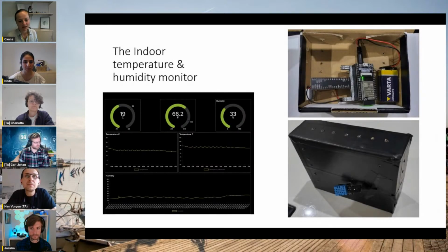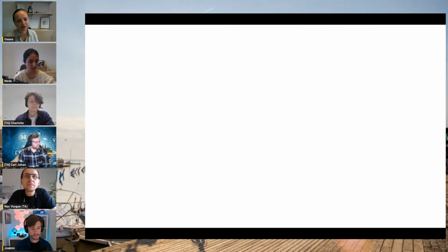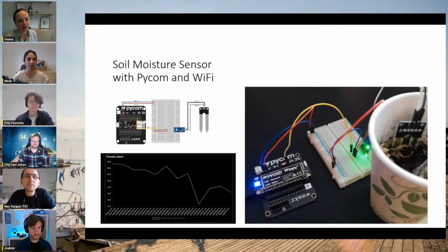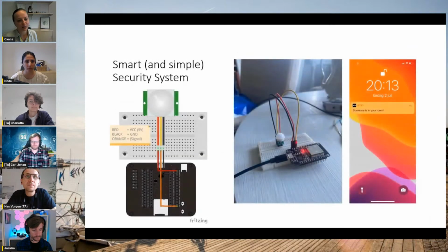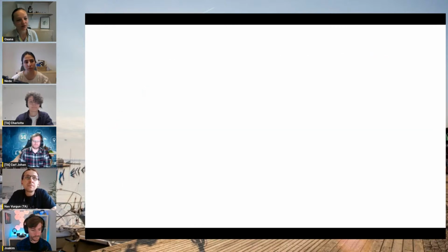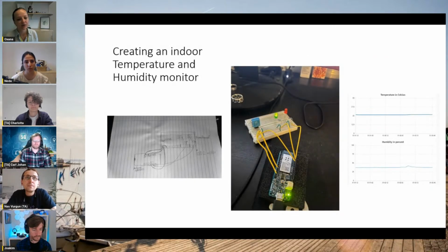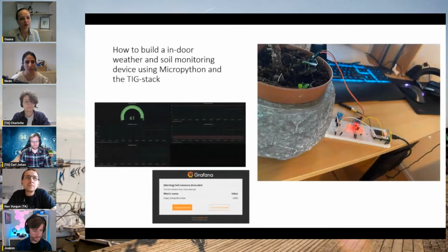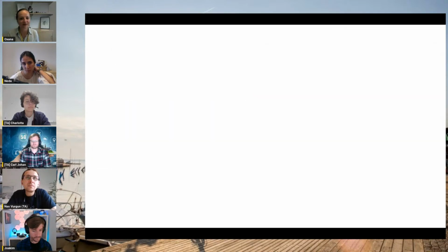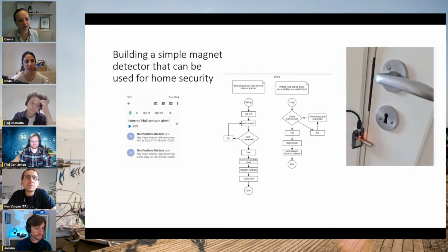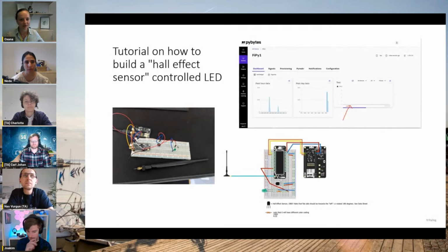So for instance, in this round of pilot cases that we have in the lab for IoT for small companies, we have a lot of pretty simple projects with temperature, humidity, and so on, but we're still using LoRa because these are like camping sites where the different houses are distributed on an island, for instance. So there are limited applications. Yeah. So Wi-Fi is only if you are literally in your house, potentially, if you have very good coverage of Wi-Fi. And with LoRa, you can go bigger.